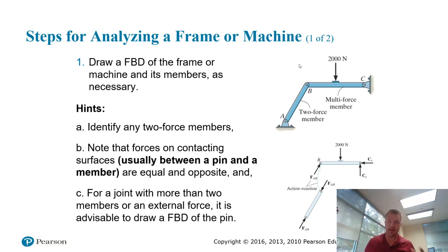And remember, if something that looks like a truss has at least one multi-force member, we would refer to it as a frame. So really, it's just a matter of using the fact that if the frame's in equilibrium, each piece is in equilibrium. So we want to do whatever it takes to break it apart and draw free body diagrams that are statically determinate.